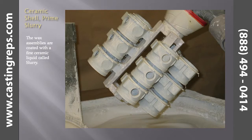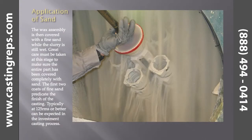Ceramic shell, prime slurry. The wax assemblies are coated with a fine ceramic liquid called slurry. Application of sand. The wax assembly is then covered with a fine sand while the slurry is still wet. Great care must be taken at this stage to make sure the entire part has been covered completely with sand. The first 2 coats of fine sand predicate the finish of the casting. Typically, a 125 RMS or better can be expected in the investment casting process.